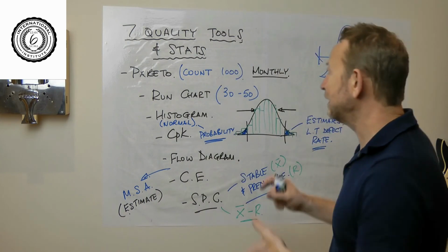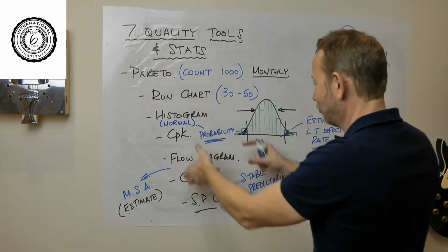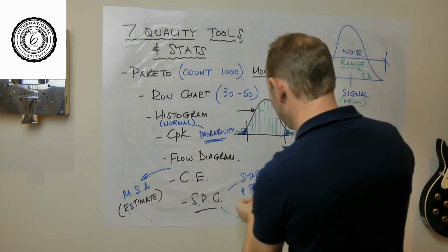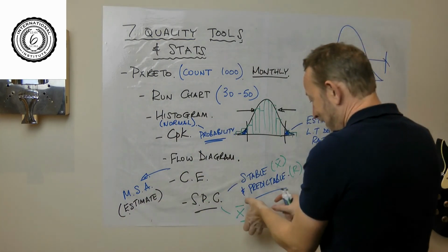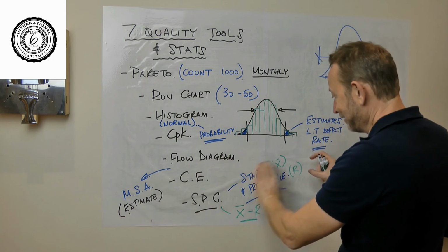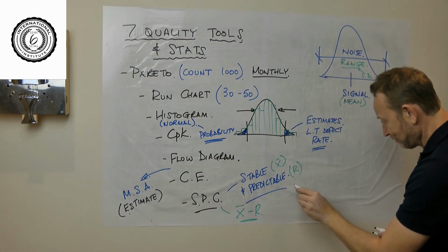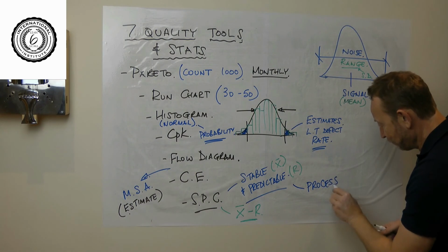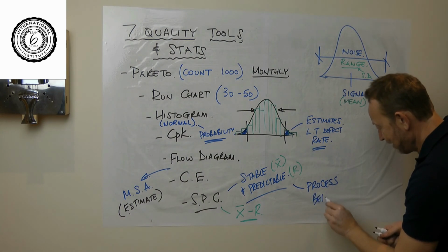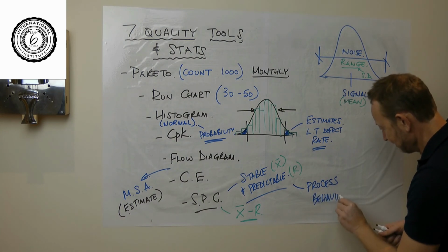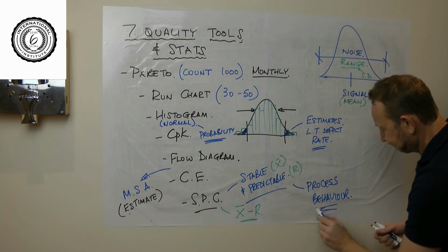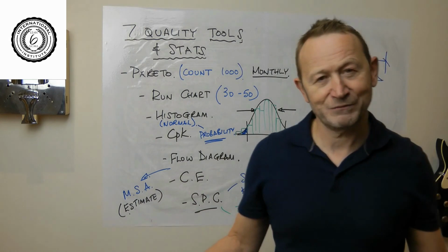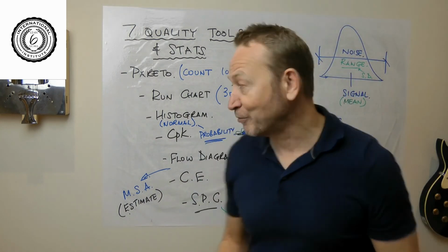What I'm doing is using them to make sure that constantly I've got good estimates of what's going on. By the way, the X bar R chart is an estimate. Another word for it? It's an estimate of your process behavior. And it's telling you whether there's something important happening to your process, but it's an estimate of what's going on.